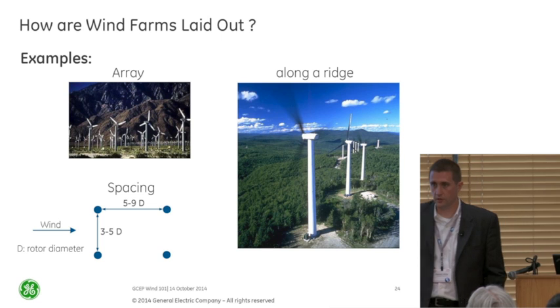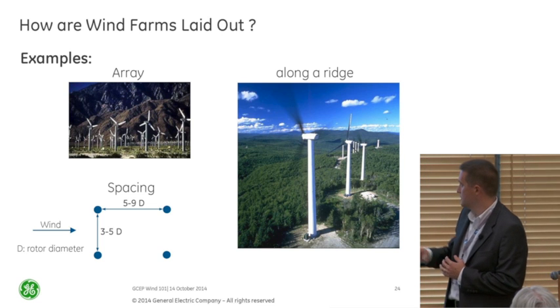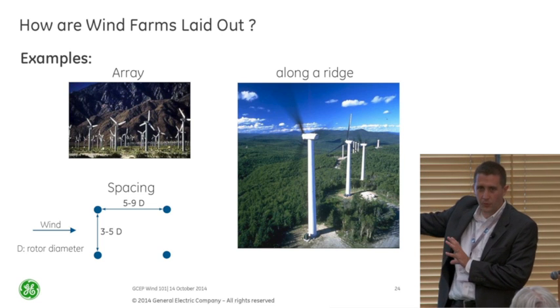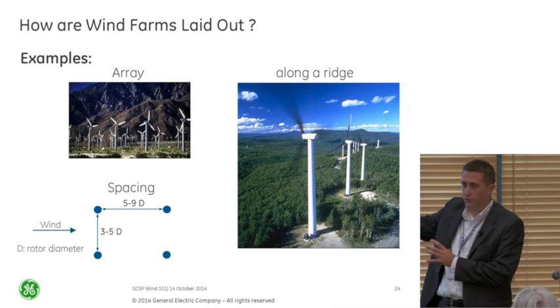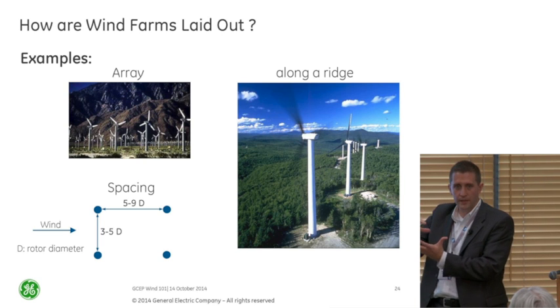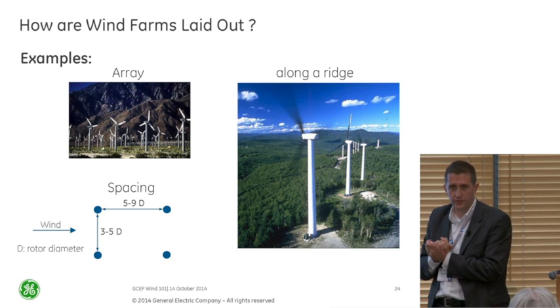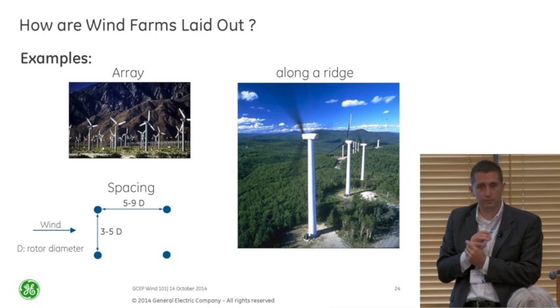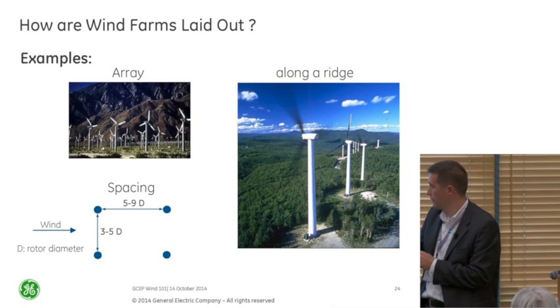So remember we talked a little bit about different ways the wind farms are laid out. Here's some basic wind turbine spacing rules. So if you have a predominant wind direction, you'll want to keep the turbines perpendicular to that, 3 to 5 rotor diameters away from each other. Say if 100-meter rotor diameter, you're saying site these things 500 meters apart. So that's quite a bit apart.